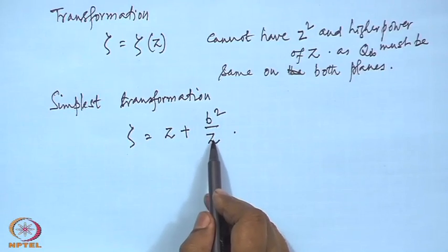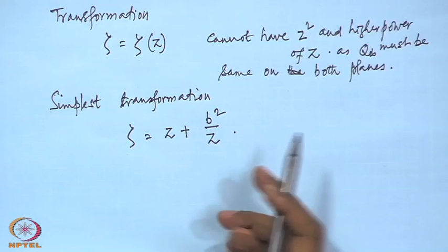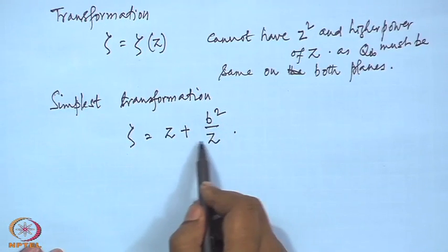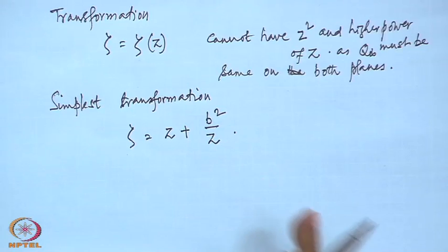We need one corner; an airfoil has a corner, a trailing edge. So, that is why you must have one critical point on the surface of the circle, and at least this term will give us a critical point, otherwise there will be no critical point. That is why this first term, hence it is simplest.